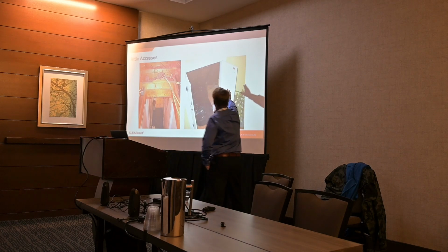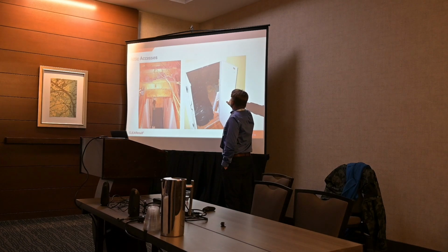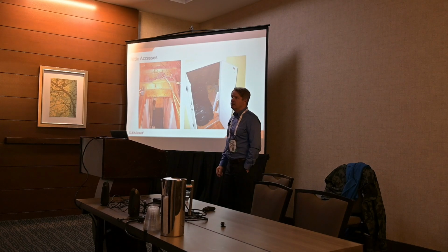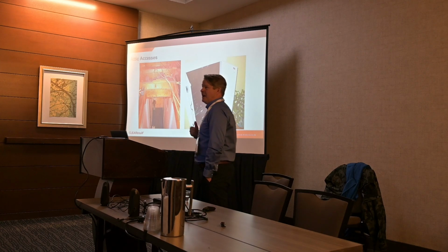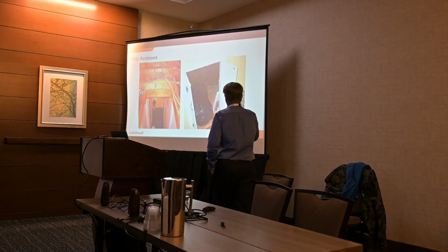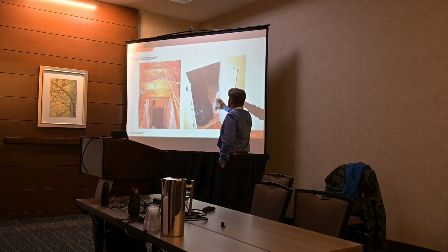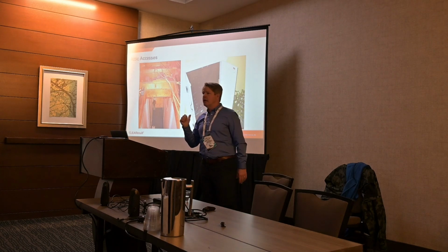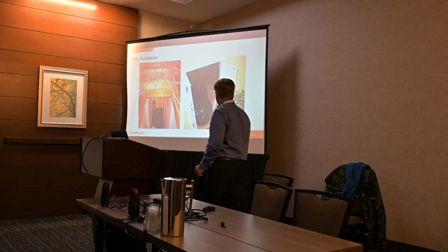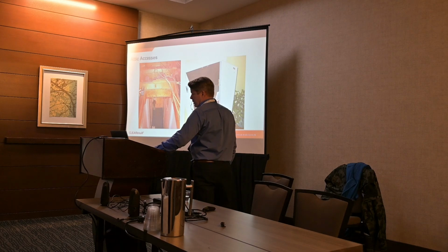When we see accesses like this, what's our plan for getting that tight and well insulated? I'm asking you because I don't have one, right? I don't know what to do with that. It's a mess. What I would recommend is just pulling those doors off completely and putting a hatch there with barrel bolts, right? That way we can use Q-line with carrier around it to make it tight. We can put a couple of inches of high R board on the back, and now it's the same as the assembly that it's part of. Okay, that's the way you'd want to go there.